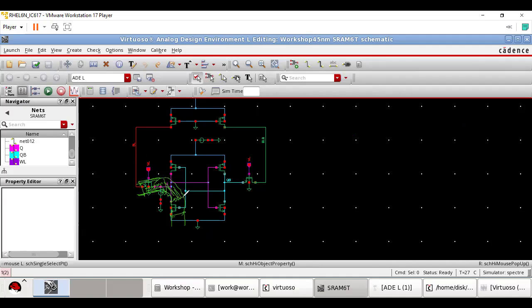Ultimately, this 20 centimeter will become the bottleneck. What logically we do, if the size of this pipe is 24 centimeter, then the size of this pipe should be 30 centimeter, so that whatever comes from here should easily pass through this pipe, right?